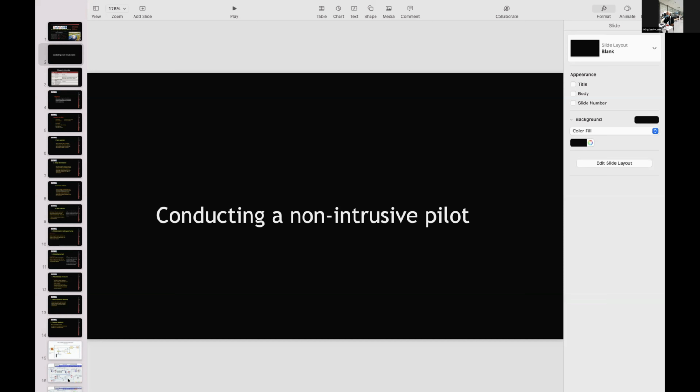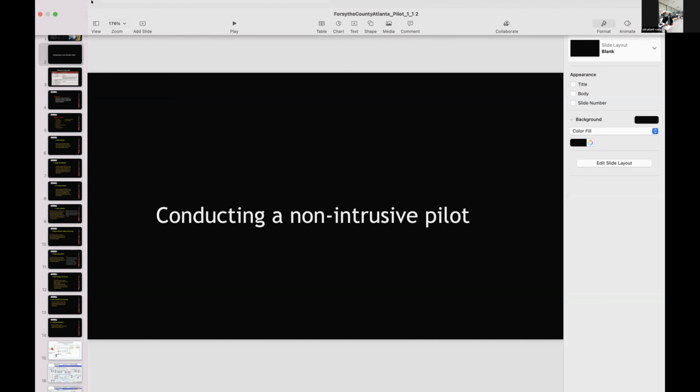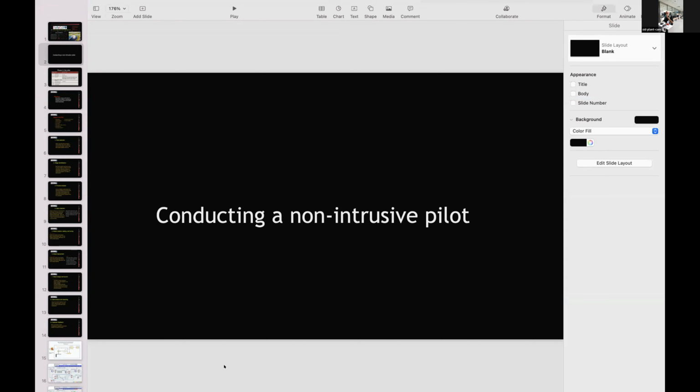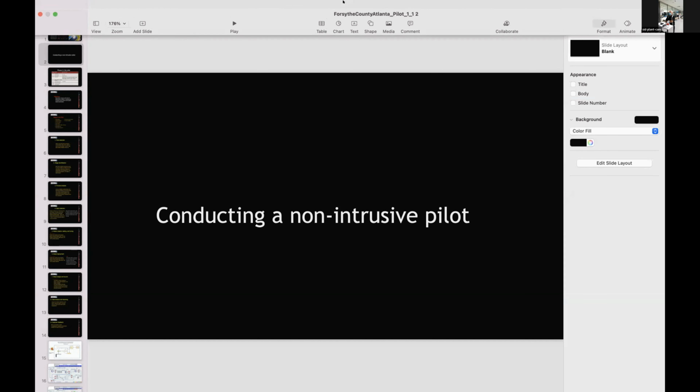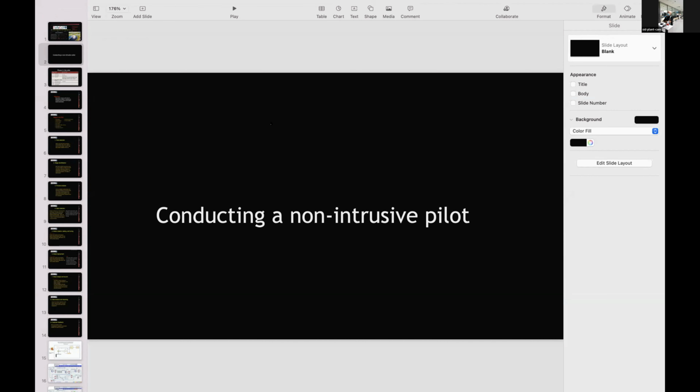That's a more difficult attack to detect. And we can detect those kinds of attacks, which are called multi-point attacks on multiple stages simultaneously. But let's say there's a tank that's almost full, but I'm nefarious and I want to overflow that tank. I can take all the valves that are automatically controlled, throw them in manual. I can put my pump into manual and overflow that tank. Your system may detect there's a problem, but it can't do anything about it, right?